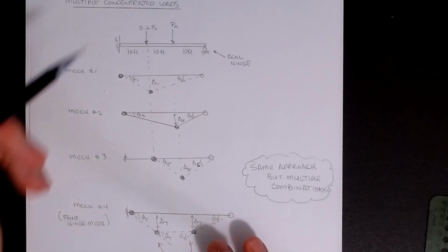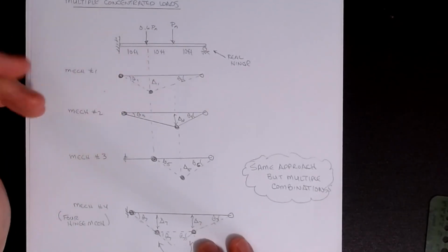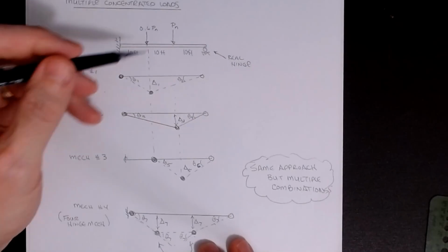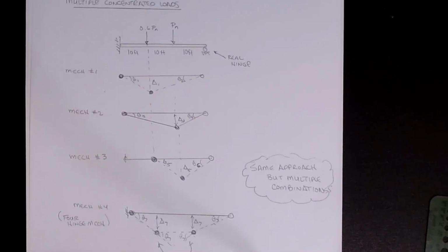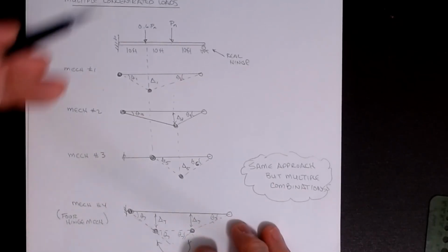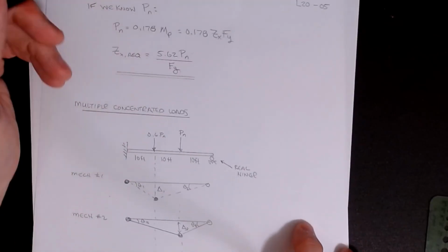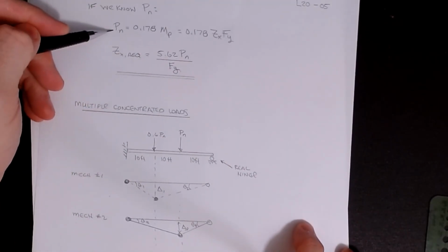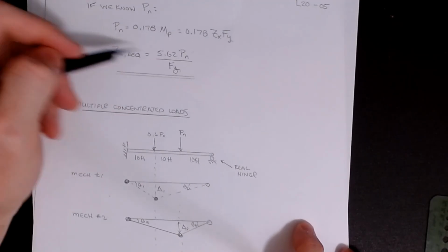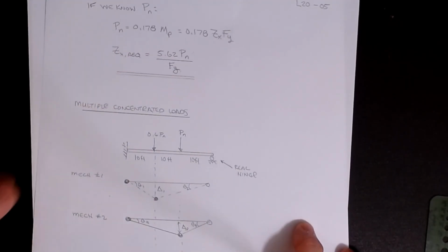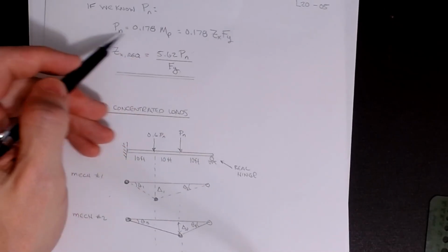Now, one thing to also point out is we have no factors of safety anywhere on this. I don't have reduction values. I don't have 1.2 dead, 1.6 live. We don't have any of that. So if you were to truly want to work this problem, you would probably want phi and P in the formula up here, and then you would probably want to play the game with Pu. Okay, and that would be a way that we could apply AISC principles to this. But just the general formula, this is the way that we start to set it up.